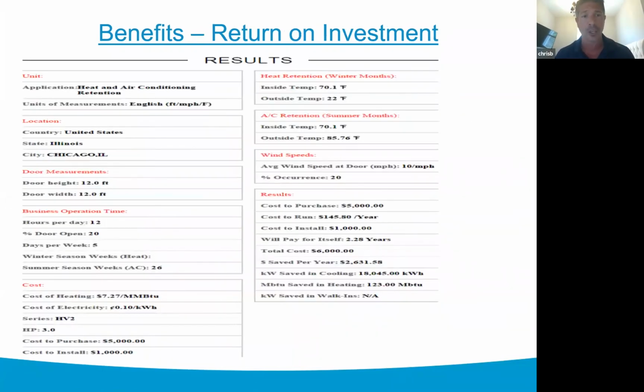So from here, we can say, hey, all right, doors close without an air curtain, and we have to get that space back to room temperature. That heating and cooling system has to run, okay? So without an air curtain, we have a greater loss, as you could just see on the previous slide, versus with that air curtain, okay? So that runtime is reduced on the main HVAC system.